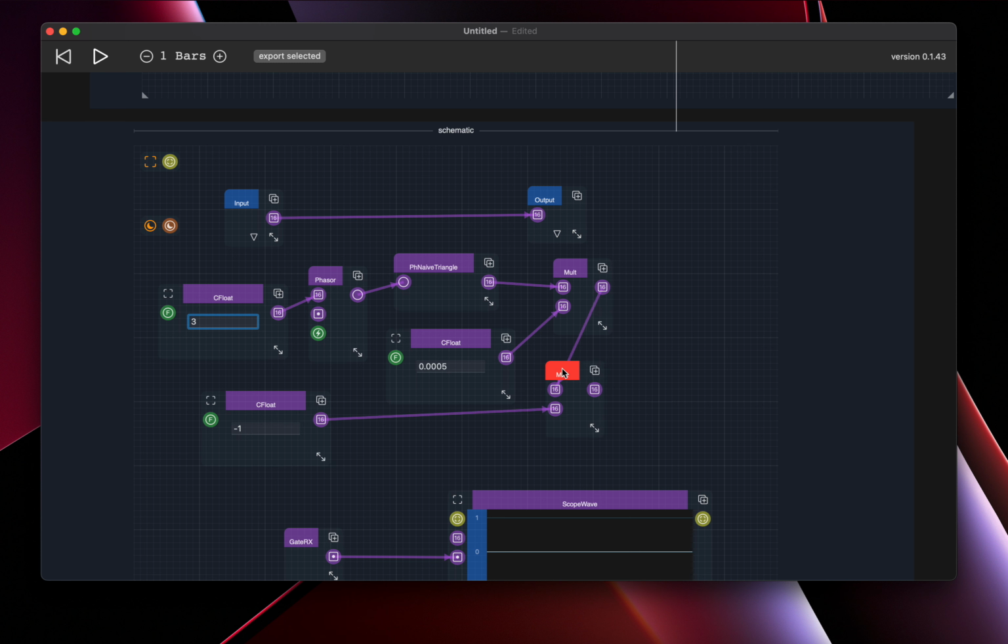And now, because this is a delay, and the triangle goes from -1 to 1, this would cause values here to go below 0. So we'd have a negative delay, which we don't want, because that will give us some noise, some old stuff that's still in the buffer.